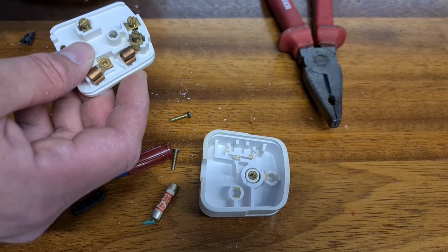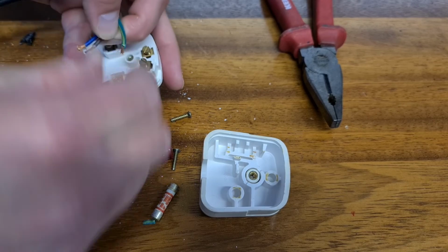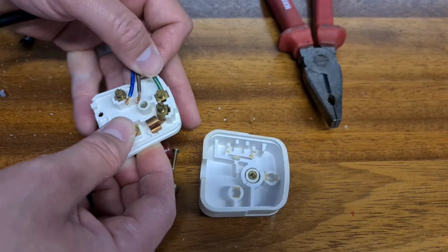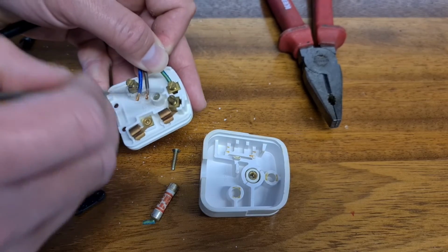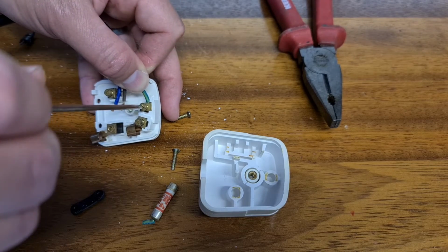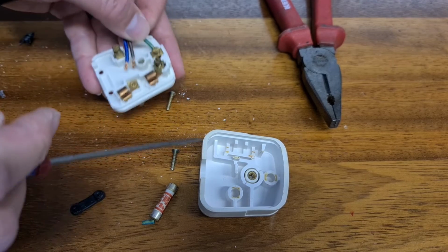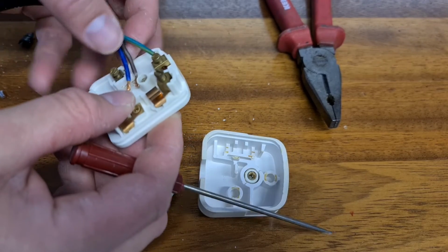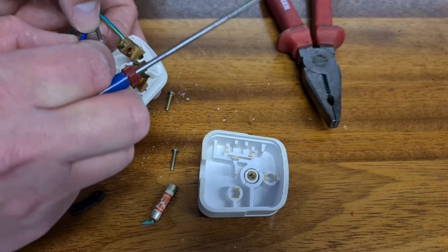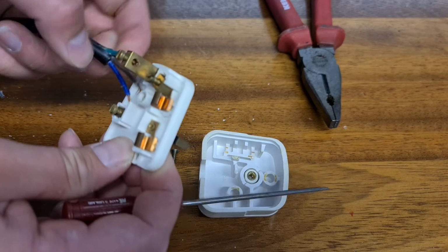And what I'm going to do is I'm going to put in, let's go with the earth wire. A small twist, just to make sure that all of the little tiny wires are together, and then I'm going to poke it in until I can just see through the little tiny gap on the side that it's poking through. Then, holding it still, I'm going to wind this up until it has got a firm grip, and a small pull just confirms that it is.